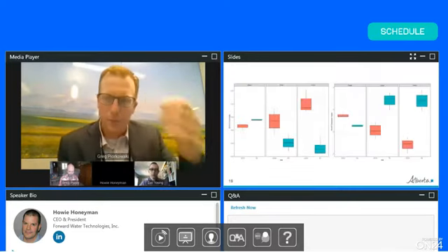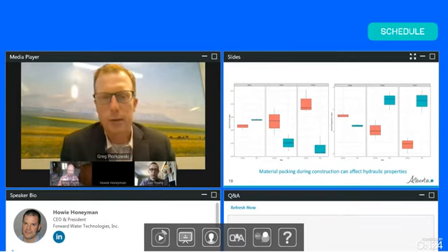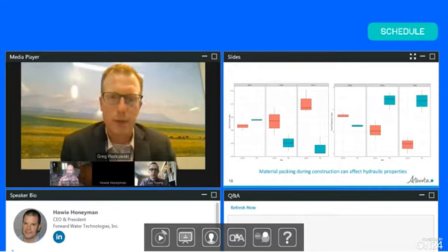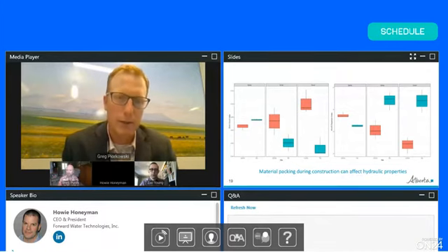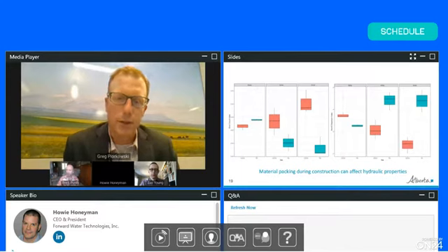I'm just going to briefly go over this, but what we're also doing is tracer studies just to look at how solutes flow through that material. All I really wanted to demonstrate here was that these systems tend to behave differently between the north and the south. Whereas at the northern sites the barley and the hemp had more short circuiting than the wood, it was the inverse at the southern site. So this is likely the way that the material was packed during construction can affect the hydraulic properties. That's all I wanted to show there.